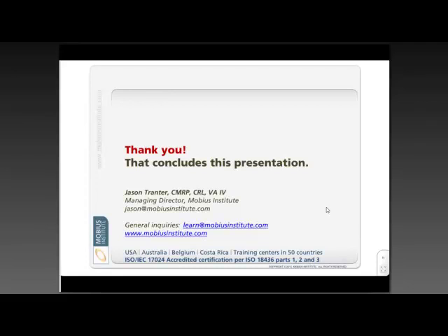Good question. Okay, now the short answer is that you should think about your machines, think about the fault conditions or the failure modes that you are concerned about. And you need to take measurements frequently enough to ideally get at least two measurements while that machine is transitioning from being healthy to failing. That's the minimum you want to achieve.